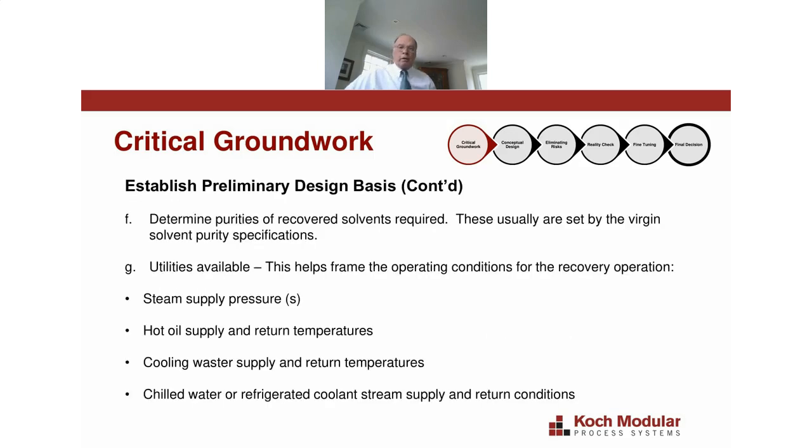Okay, so again, that is the first step, determining what your solvent mixture is, what all of the impurities are, and its flow rate. The next step is to determine the purities of the recovered solvents that you want to get back from this recovery and recycling process. And typically, it's normal to expect that the goal would be to purify the recovered solvents to the same set of specs as the virgin solvent purity that you buy if you were to buy a virgin solvent mixture.